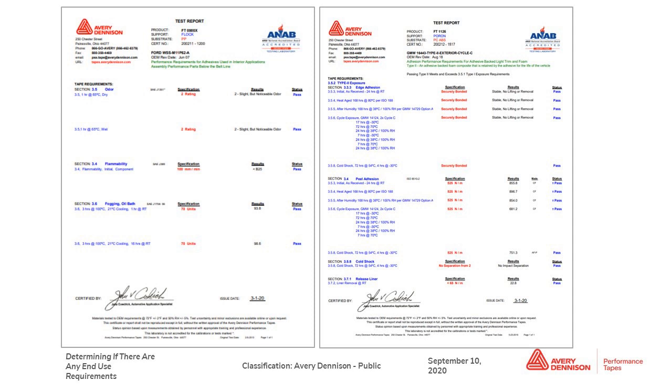So does it stay securely bonded throughout these different types of conditions, like 24 hours at room temperature? That's very easy. Heat aged 168 hours at 80 degrees Celsius. There's a humidity requirement. And then there's a cycle exposure where they want it cycled twice through negative 30 degrees Celsius up to 70 degrees Celsius, a humidity situation, back down to freezing, back up to humidity, back up to a high temperature, more humidity, and then repeat that. So you can see how these OEMs are accounting for all the different conditions that might occur.